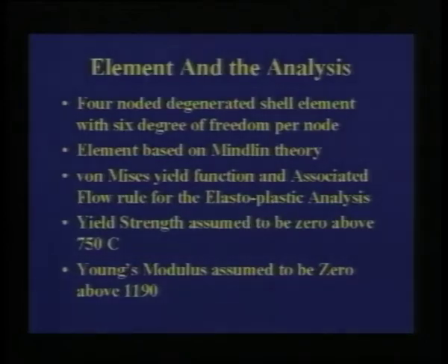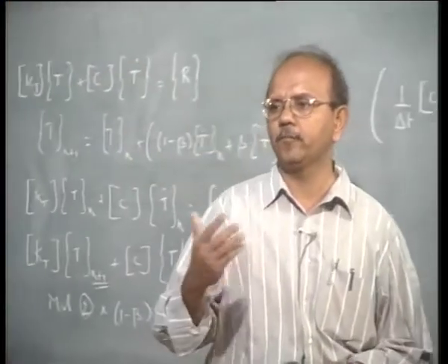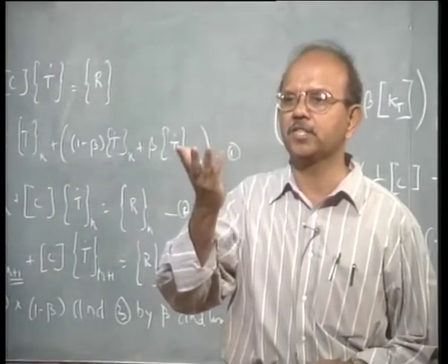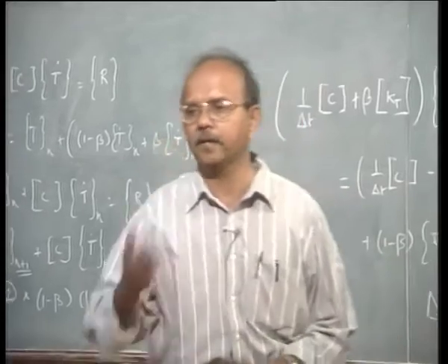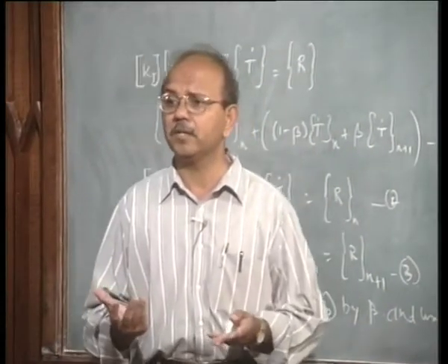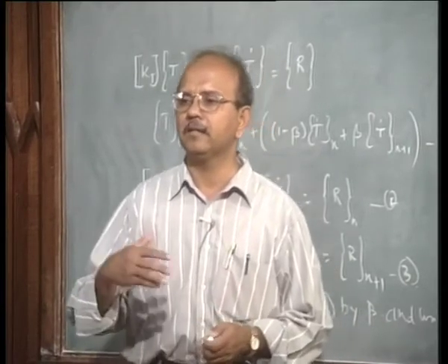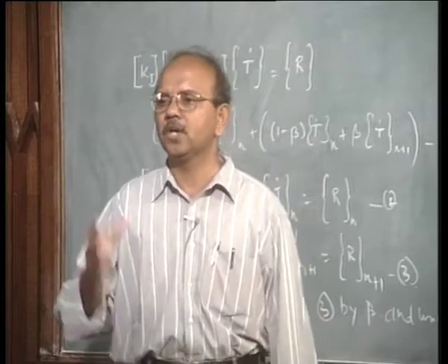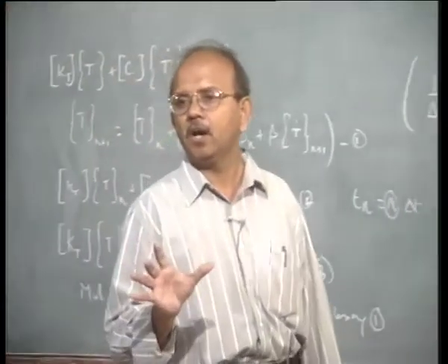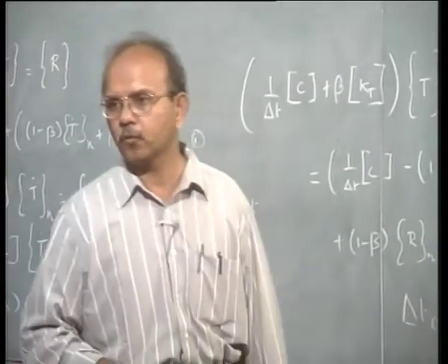For the time being, you can assume that when the shell becomes thicker, some of the assumptions that you make on shear deformation of the shell, or in other words plane sections remain plane, for a plate it may not remain the same, then the plane sections need not remain the same. So you have certain adjustments that have to be made, and there are theories to make these adjustments. We will study in a nutshell about these things later in the course, maybe after about 3 or 4 lectures.